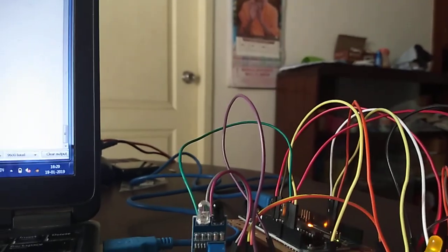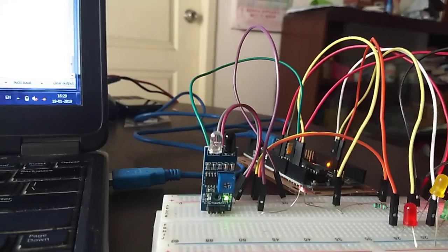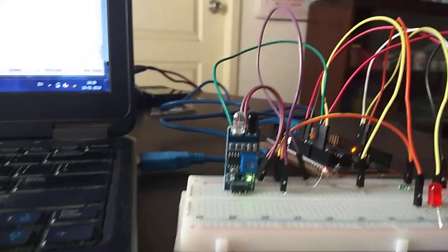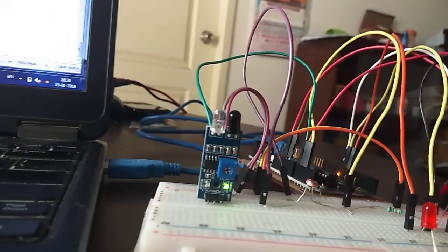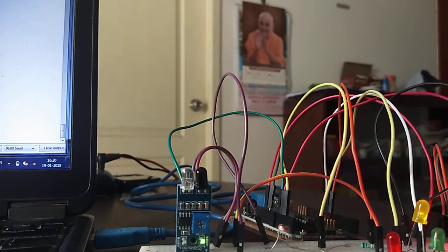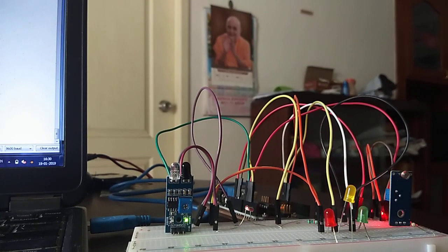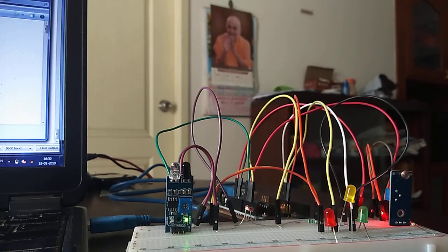The good thing about photo sensors or LDR is that we can hide them under our rail tracks. So I prefer those, but the only problem with them is that the intensity of the light will change during the day, and it may not work as we expect. So we have to make sure that the light source is constant in our layout.